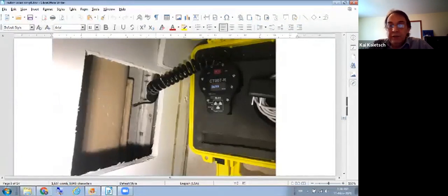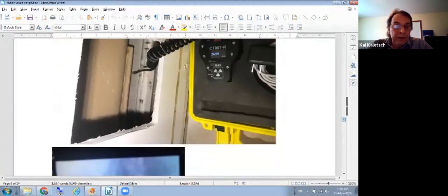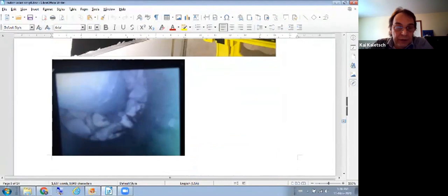After that, he is putting a borescope down, and he found that there is a gap between the concrete slab and the drain. So after that, he sealed that gap, and that helped the radon levels.